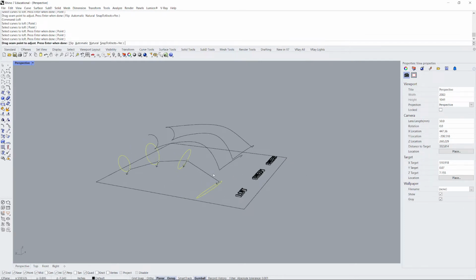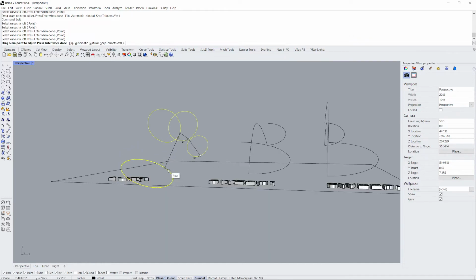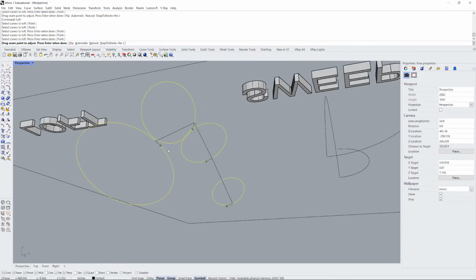And then as you hit enter, one thing to pay attention to is these are the seams. So you really want them to line up with each other if it can. If you can get them on the quadrant of these circles, it's great.